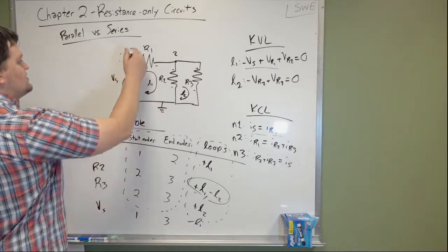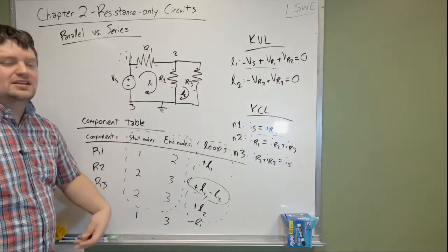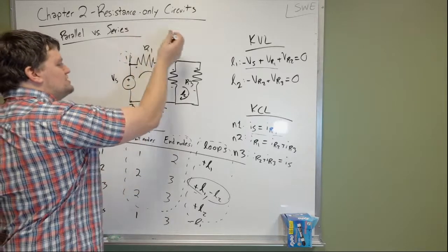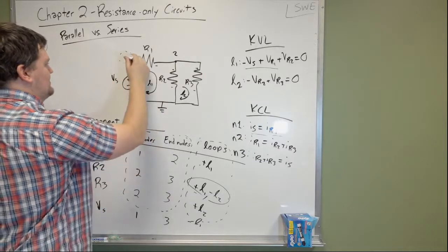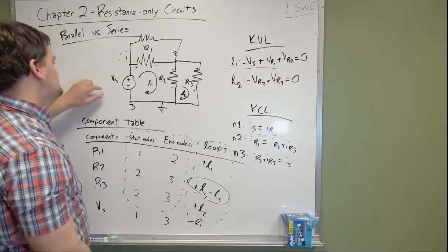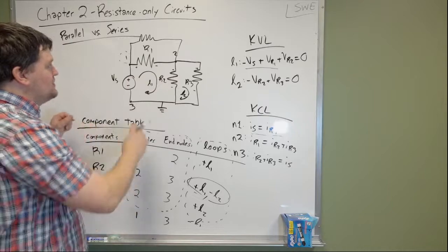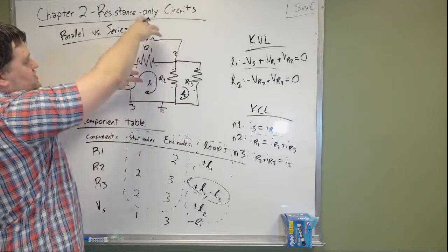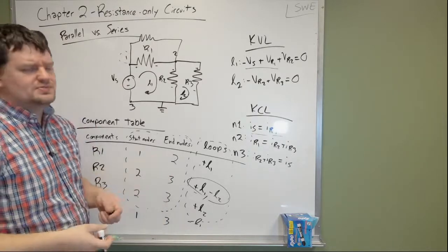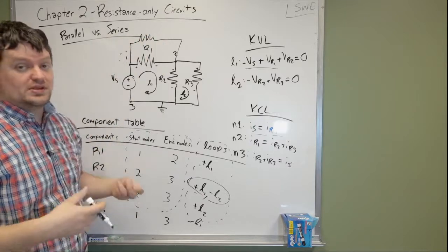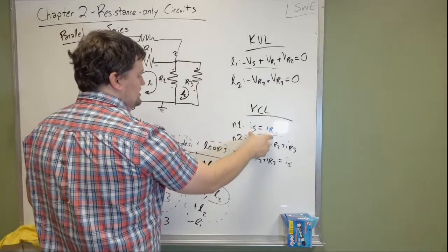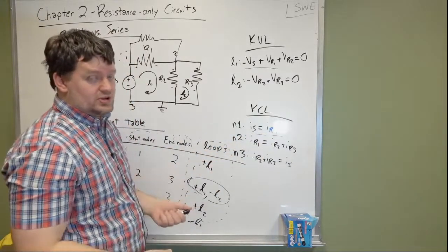Okay? Now, what if there was another piece coming in here like that? Well, technically, yes, they are still in series, but you have another direction for currents to go outside of that. Technically, these two components are still in series because the output of this one is the input to this one. You can collapse all these by doing an equivalent resistance, bringing them together, and ultimately this and an equivalent resistor would be in series. So just keep that in mind. This relationship right here is indicative that they're in series,